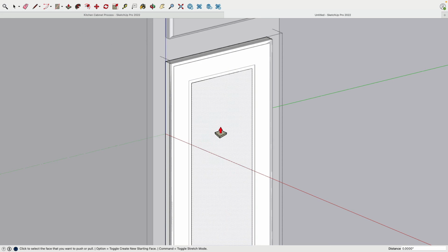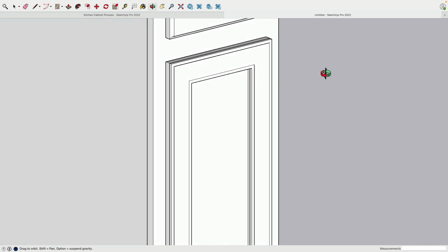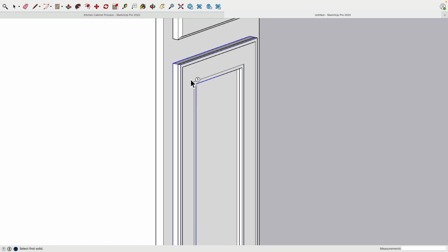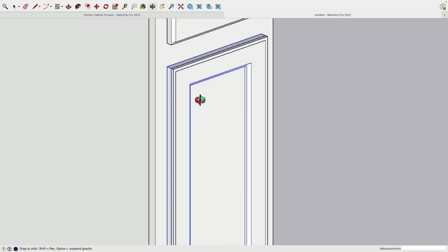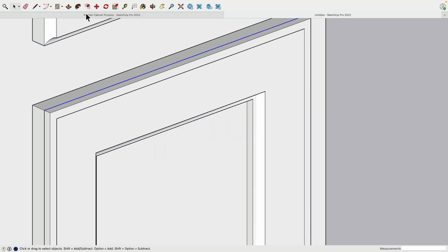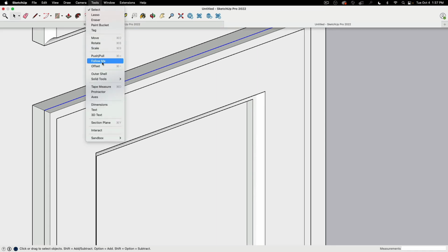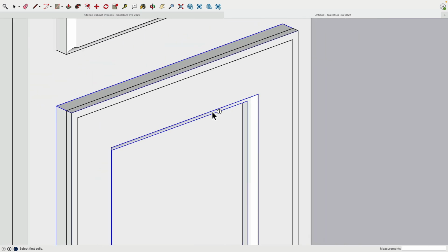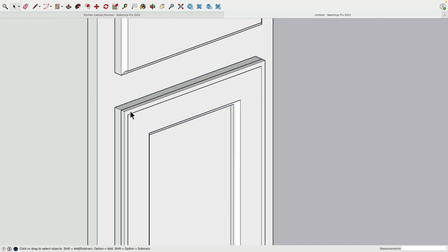Now here, this whole thing, there I need to make an offset on this body 2 inches, and then I push and pull this in by 0.5. Exit, and then subtract you from this one. Look at this. This has somewhere a little bit of an issue. I'm glad actually this happened because I can show you. See, it's this one trim piece I made, that's just junk.